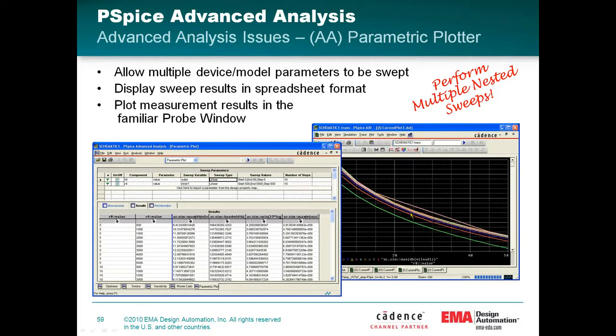But that allows you to look at your plot and see what kind of values you want to choose for these two components to achieve a certain result. So if, say, this line was a 200 megahertz bandwidth capability, and you wanted to just stay above that, and one of your resistors was a 10 ohm resistor, that would be this line here. You could use this green curve to see what resistor R2 was, for instance, to give you the value of those two resistor pairs to hone in on that particular parameter.